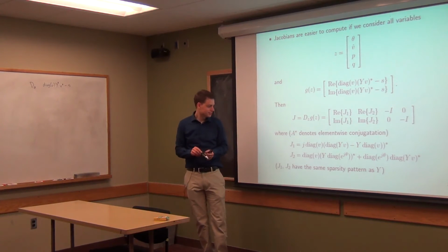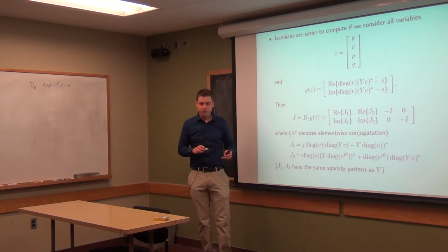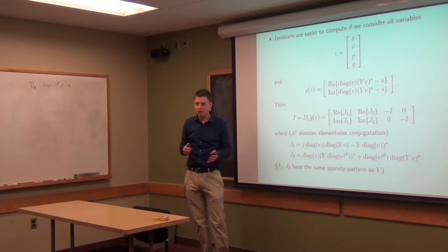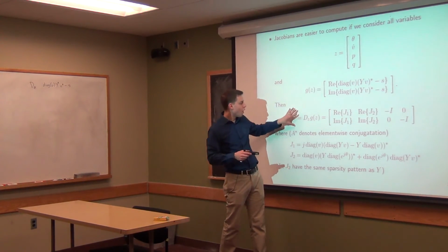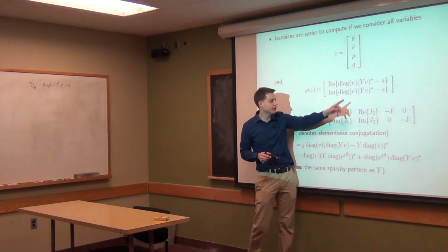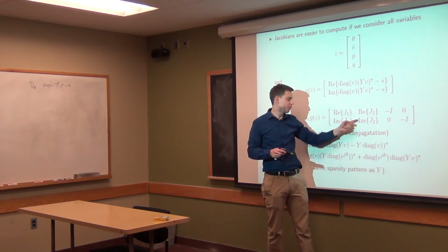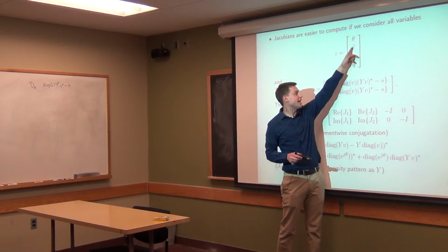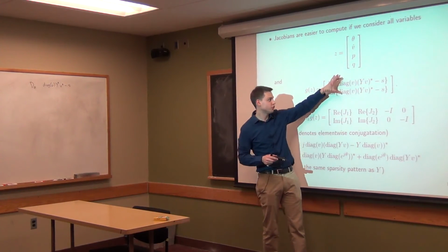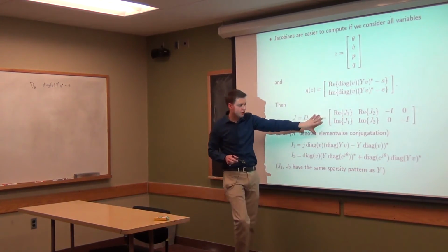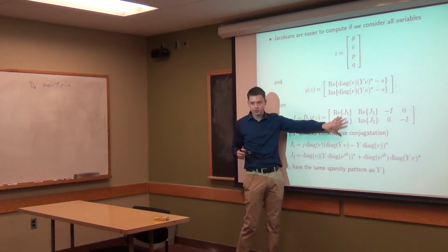So J1 and J2 are just defined as this. They're Jacobians themselves. They are with respect to one part of this, so it's the theta entry for this row, the v hat entry for these columns, the theta entry for these columns, and then you have the real and imaginary portions corresponding to the two portions of this function. They are themselves Jacobians, yes, but really I'm saying the whole Jacobian is just going to be defined like this.